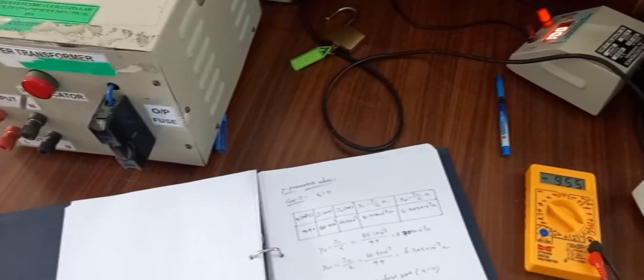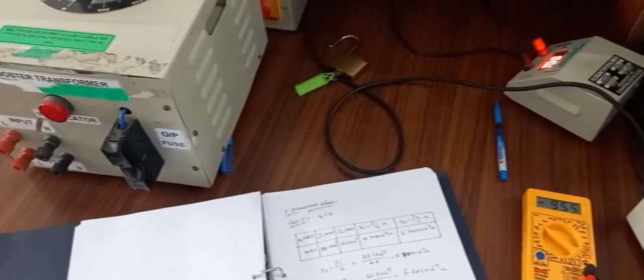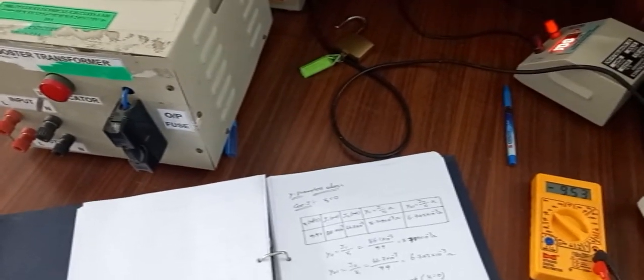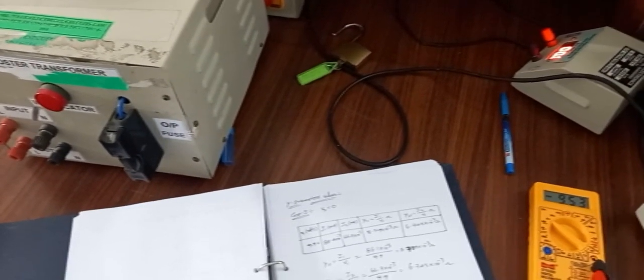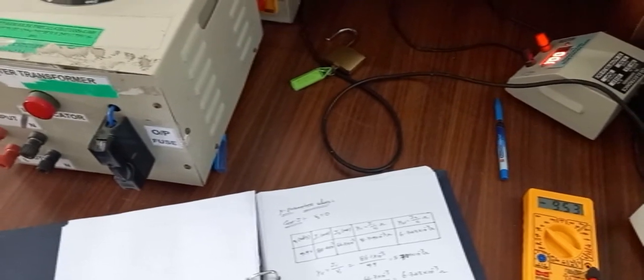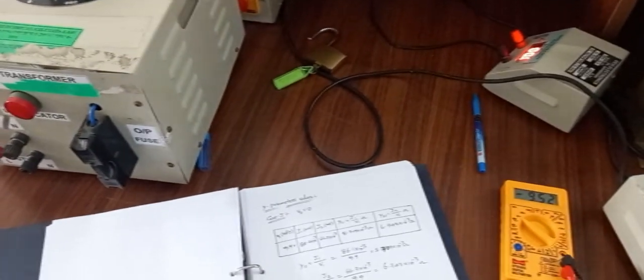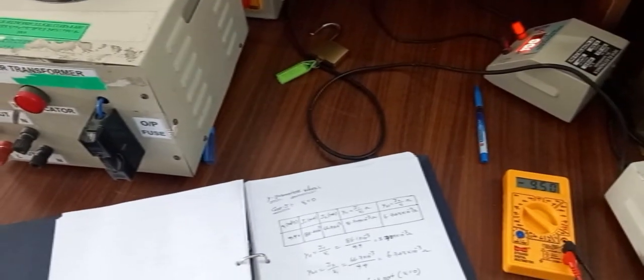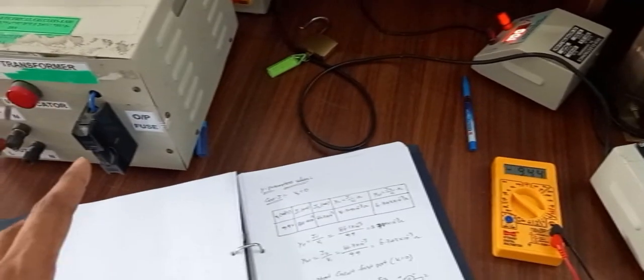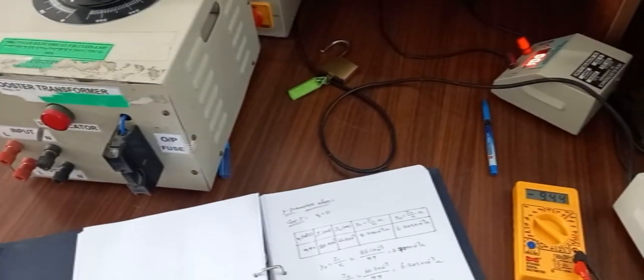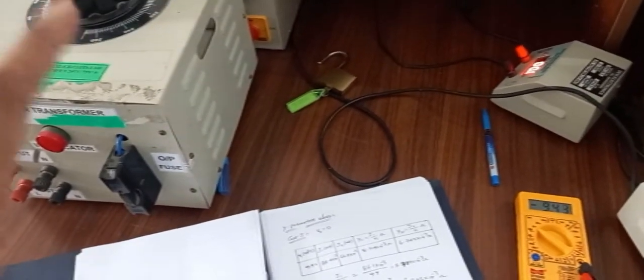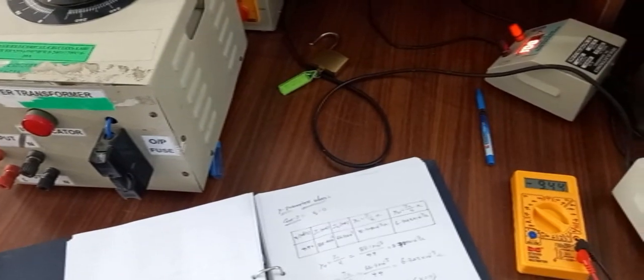So when we are calculating impedance values, Z parameters, at that condition we do an open circuit condition. At that particular condition we are measuring the voltage V1 and V2 values. When we are doing a short circuit for admittance in the experiment, we get I1 and I2 currents. Okay, that's it.